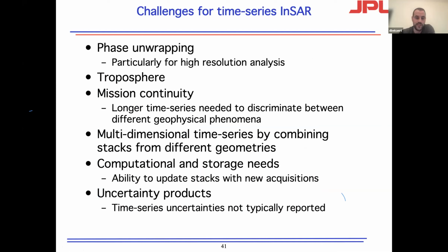The other thing is the propagation delays. So troposphere is present for all the sensors. If you go to L-band, you also have ionosphere, but if you're looking over large areas, ionosphere is also present, but definitely we can in part correct for it using the approach what ISCE is doing with 2 frequency bands, or by doing a split spectrum processing as demonstrated in the previous course. For troposphere, generally can estimate it from the data, but you're making assumptions. So that's where it's challenging. You could use auxiliary models or using the time series approach, but those reduce it. It's not yet removing it completely. So that's kind of an active research area in the community still.